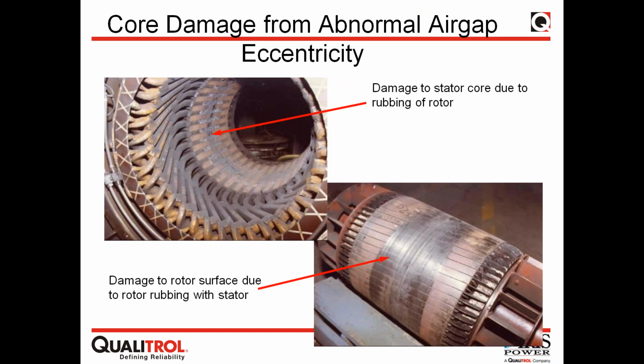Foundation moving, and so on. So in any case, the ultimate problem is contact between the rotor and stator, which is not a desirable situation. And if it happens, then there might be a rotor rub, and if not caught on time, this will lead to the catastrophic failure of the motor in most of the cases.